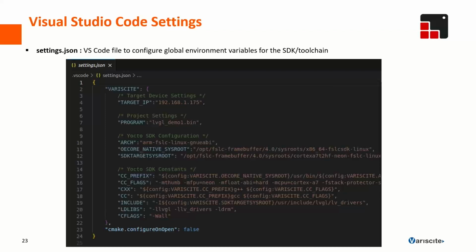We observed, in some corner cases, a mismatch of behavior when using Visual Studio Code and the native SDK in Yocto. This is because whenever you install the SDK, it ends by saying, okay, binaries have been installed, but you need to set up the environment by running this script. The script will set additional flags for the compiler.